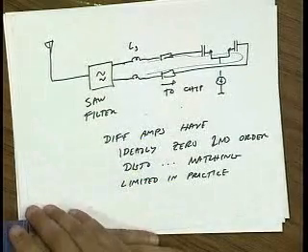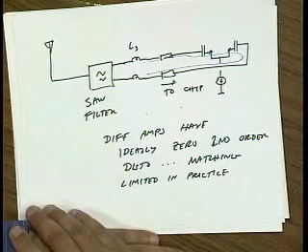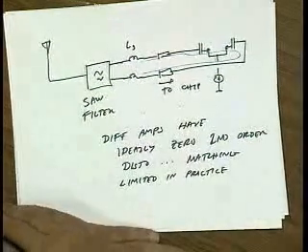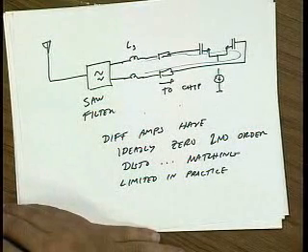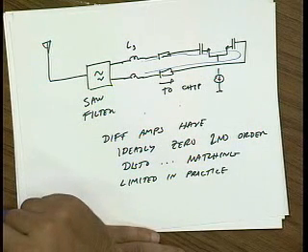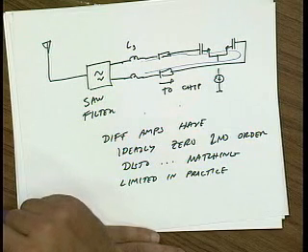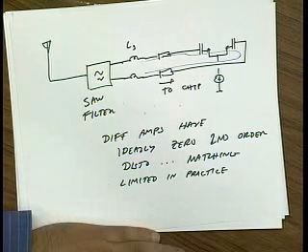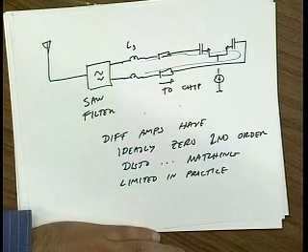Questions or comments? Okay. And as we pointed out earlier, almost everything we've said today applies also to bipolar LNA design. Very similar. So like going back to why bipolar, like someone pointed whether the same model is applicable, but bipolar also have a real component of input impedance. The R-pi. Yeah, so doesn't that make a difference, because options 1, 2 that we talked about had difficulties mainly because our RG was very small.